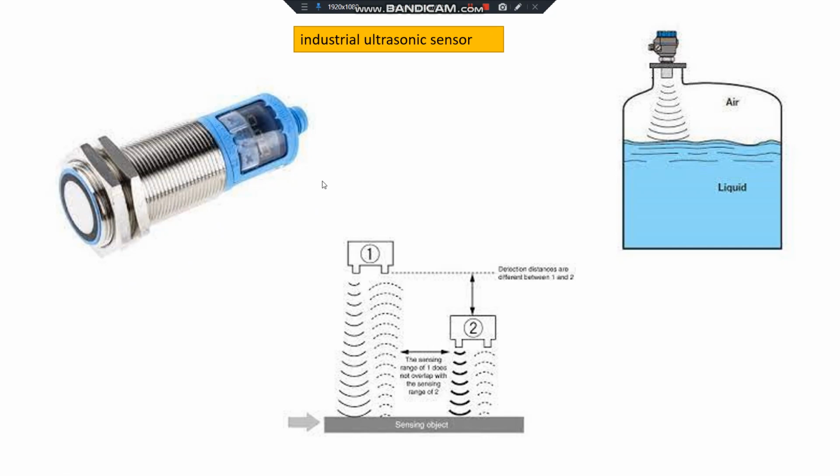For these reasons, we can use ultrasonic sensors, because ultrasonic sensors work with sound waves, and sound waves are not affected by dust, oil, etc. So if we have a problem with oil or other issues, we can use ultrasonic sensors.